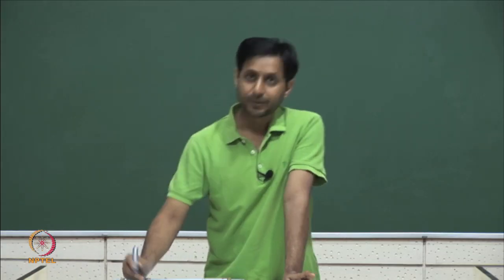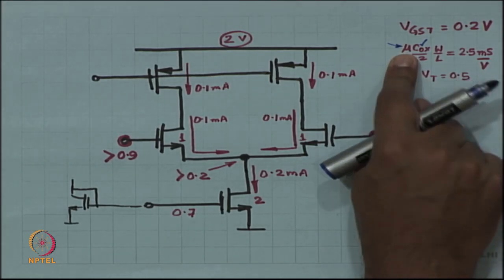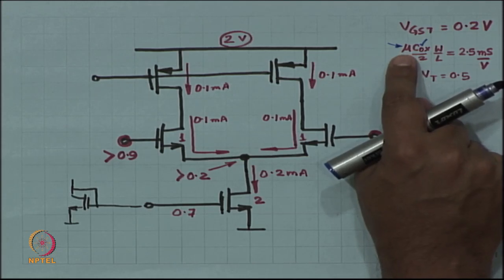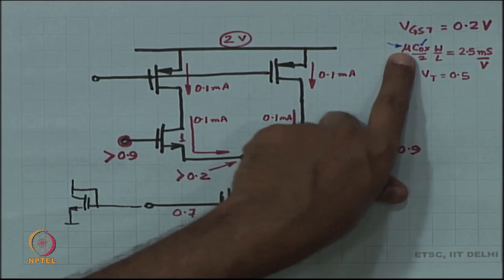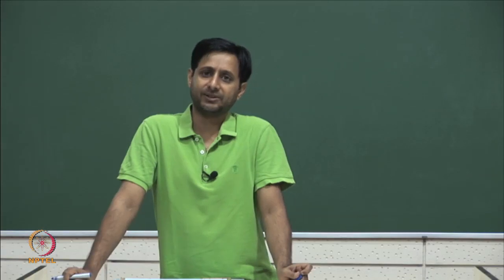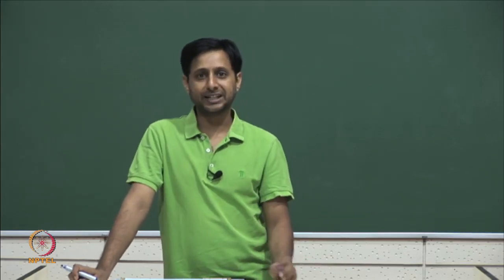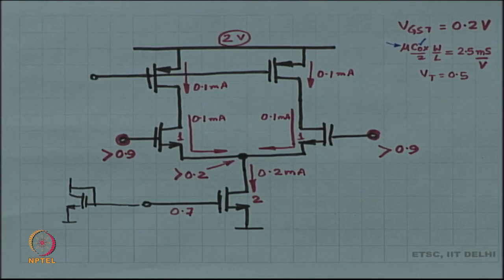So, this PMOS mu of the holes versus mu of the electrons. Mu of the electrons is the mu in the NMOS, mu of the holes, the mobility of the holes, is this parameter in the PMOS. Okay. So, in the PMOS the mobility is usually lower, holes are usually less mobile than the electrons. However, it so happens that in very fine technologies, modern technologies, 28 nanometer, 22 nanometer, 14 nanometer, the hole mobility is more or less at par with the electron mobility and sometimes even higher. Okay. In older technologies, the hole mobility is substantially lower, 3 times lower, 2 times lower, something like that.